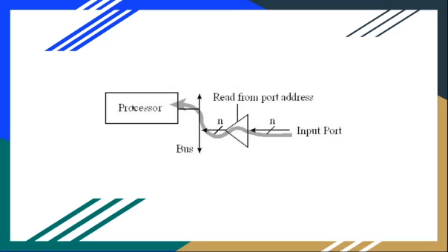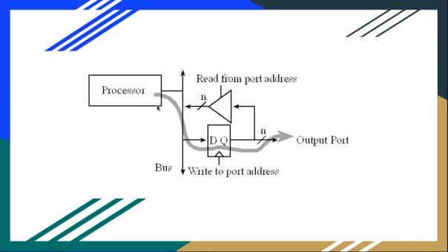So let us see how it works. One of the things software can do is to read from the port. When we read from the port, the value is mapped from 0.0 or 5.0 volt to 0 or 1 onto this bus, and we are able to read it. When we write to the port, the value, 0 or 1, is latched into the register, and this register, if configured properly, will then be able to write to the pin.